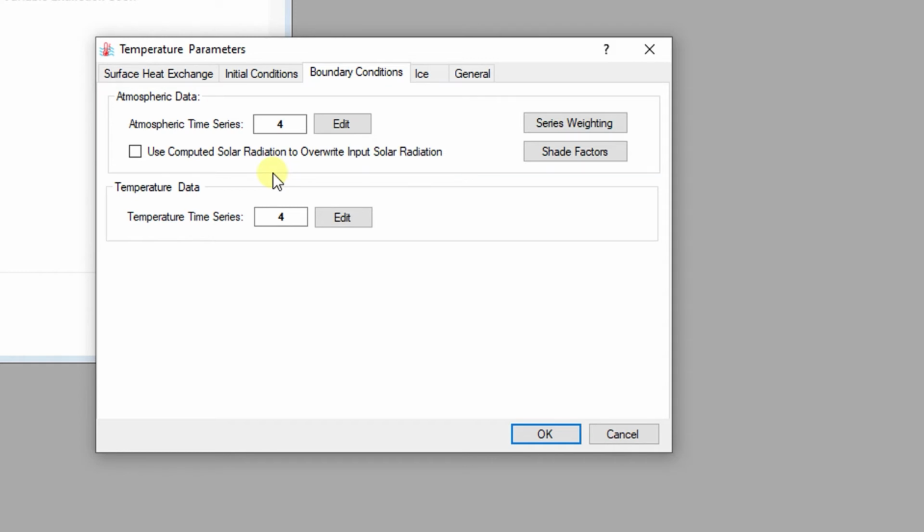The pressure solution of EFDC Plus can optionally include variations among multiple atmospheric stations in the model domain. The modified pressure solution does not make any contributions to the hydrodynamic field when the number of pressure series is less than 2, because the horizontal pressure gradient component of the atmospheric pressure is always 0.